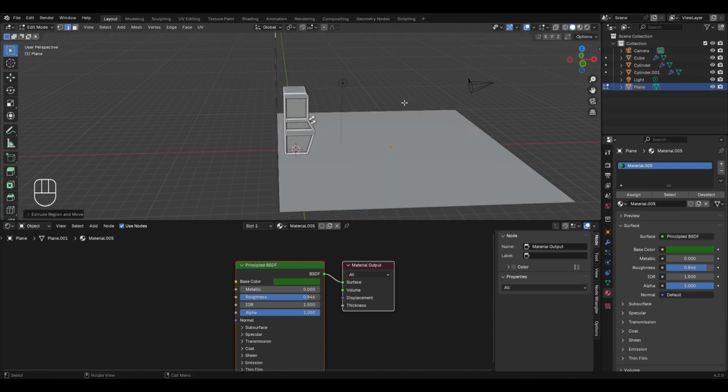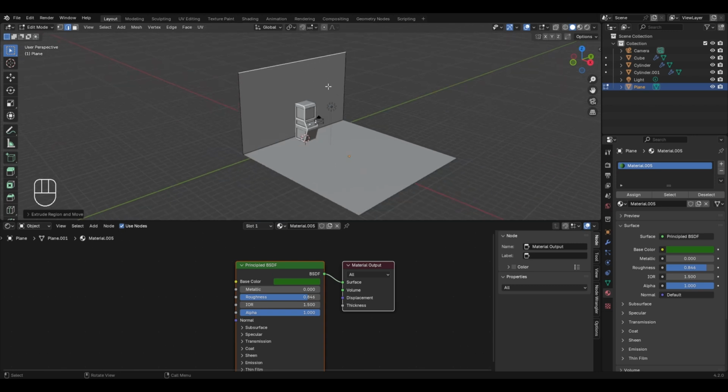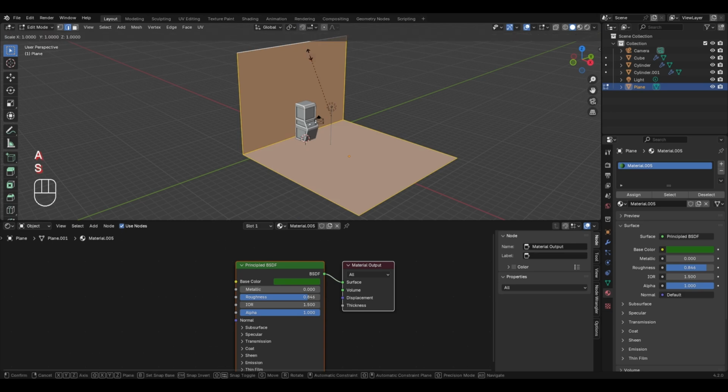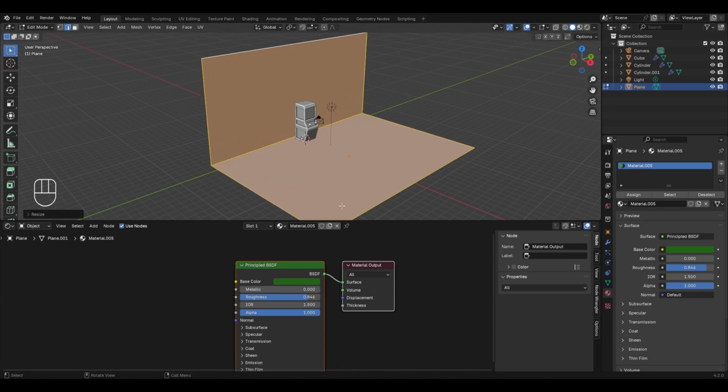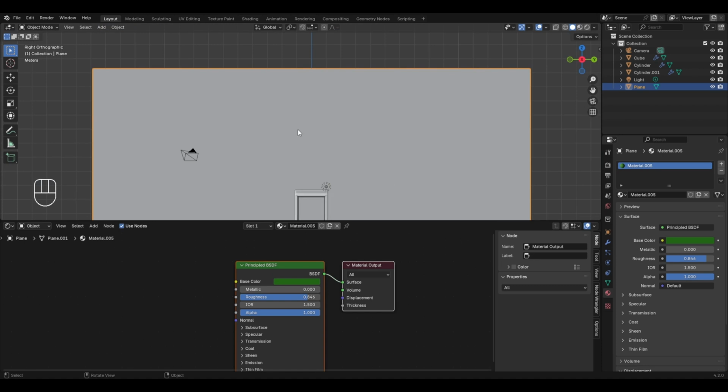Then left click to finalize, let's change the angle, and on this particular face, we'll create a text with the principled volume material. But before that, let's increase the length of this face slightly more in the z-axis. So with the edge selected, let's move it up in the z-axis like this. Also, press A to select all, and let's also scale it up in the y-axis. Then left click, return back to the object mode, and now to add some text on this wall, let's first place our 3D cursor over here.